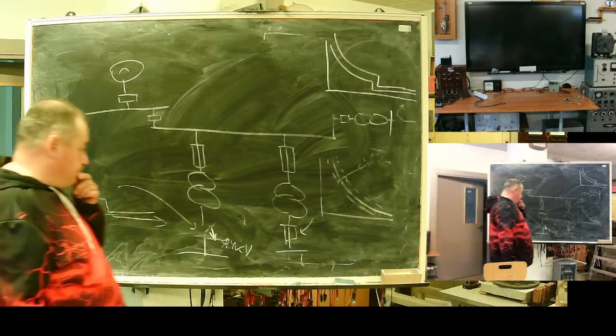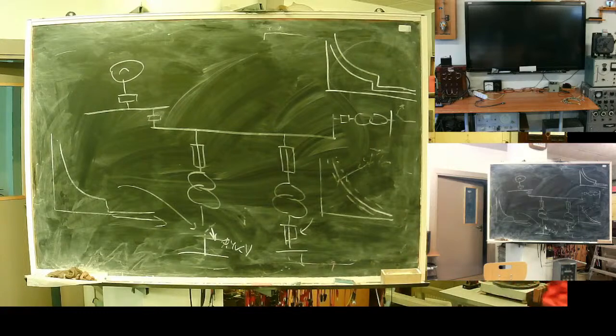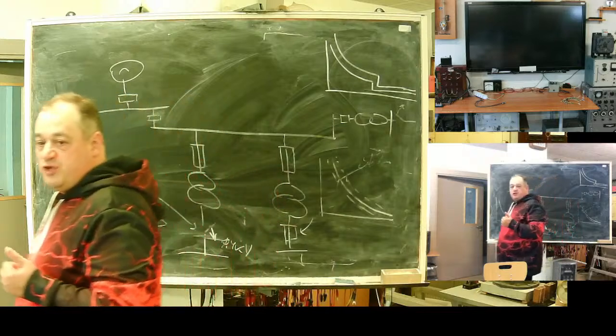Correct answer. We need to coordinate with the customer overcurrent protection and overload protection. We need to coordinate. If we have a large customer, like for example a water treatment plant, they have large, usually 6 kilovolt, large pump motors. They will have this overload protection characteristic. And we need to coordinate with the fuse.